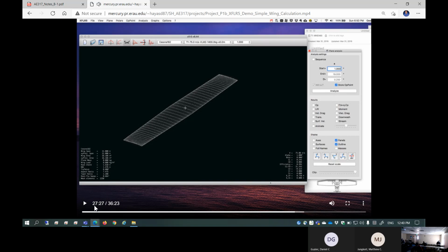So he's talking about a solver that is essentially a coupled Euler solution and boundary layer model. Panel method is an Euler solution, okay? In aero, we did the project of the flow over a circular cylinder, which is essentially an ideal flow solution. The stretch of that idea is called the vortex panel method. Vortex panel method doesn't take any account of viscosity. So you're going to have a solution, and then that solution needs to be modified based on two things. One is, of course, boundary layer behavior. If boundary layer transition or separation happens, the solution based on ideal flow needs to be corrected based on that.